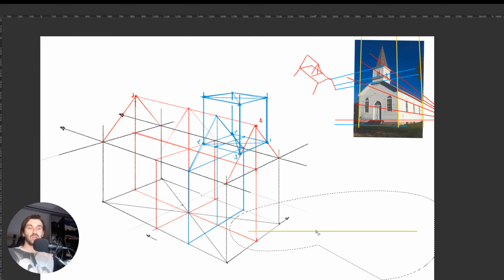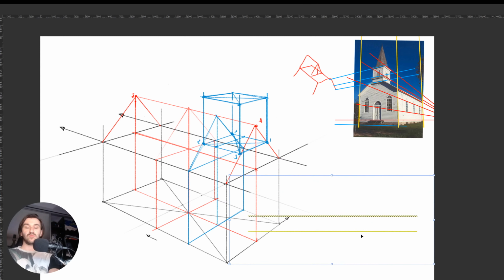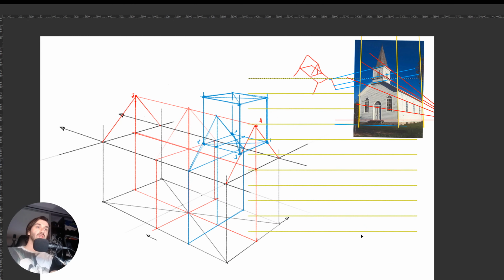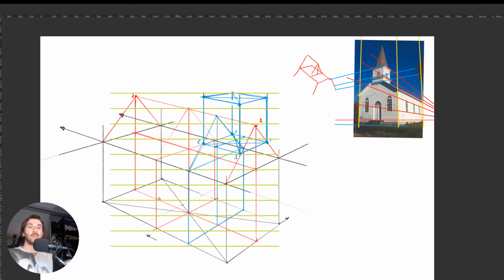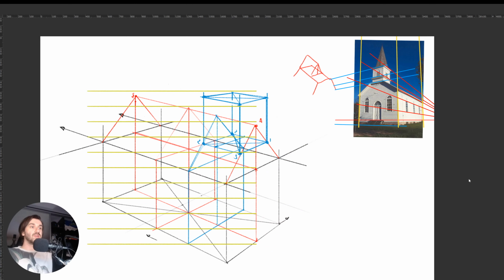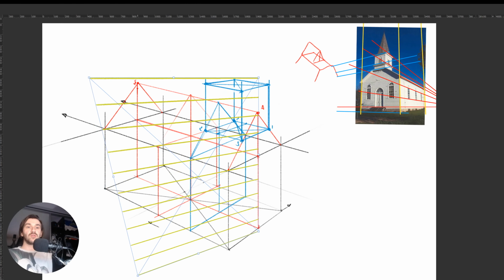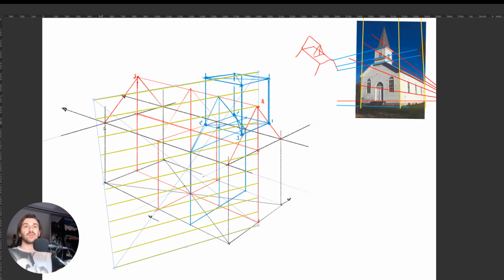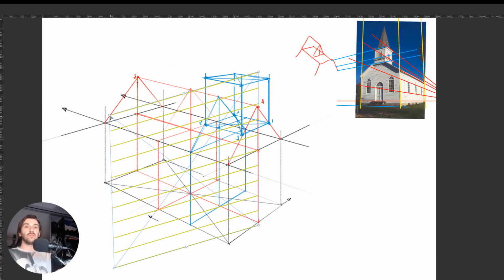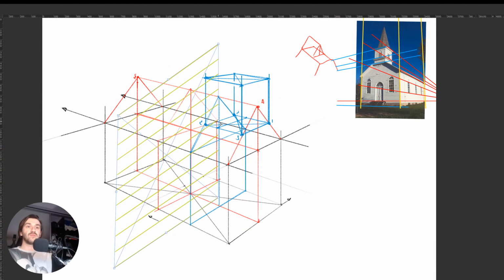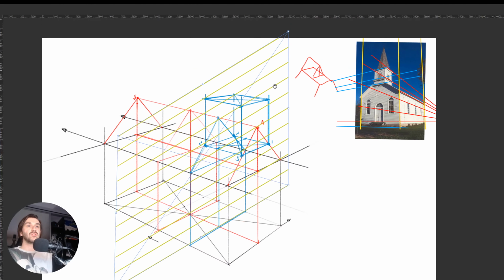So basically, if you select a line, press Ctrl Alt T, move it slightly to the top, press Enter and Ctrl Alt Shift T. It will allow you to create a duplicate of the same transformation. If I find myself struggling with the perspective, I will simply create a perspective grid, so I can match it to what I actually have on the screen at the moment.